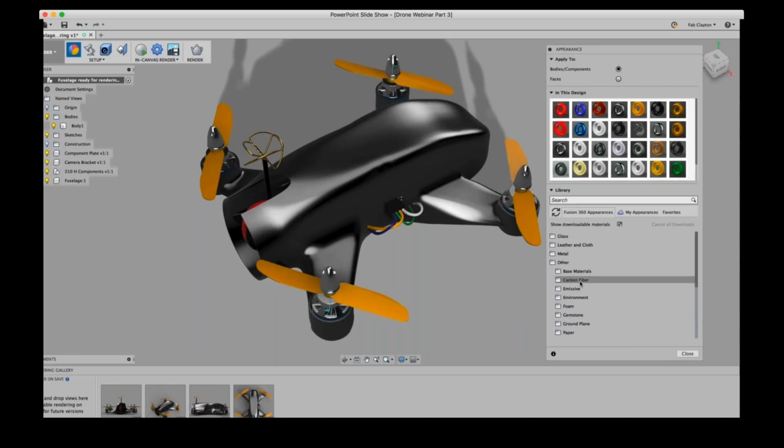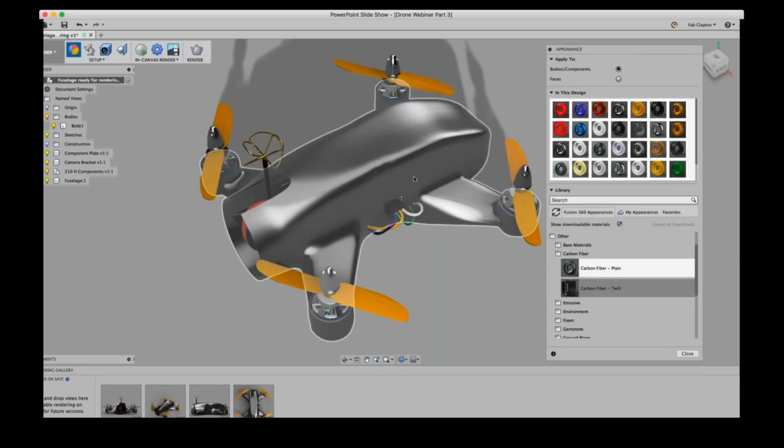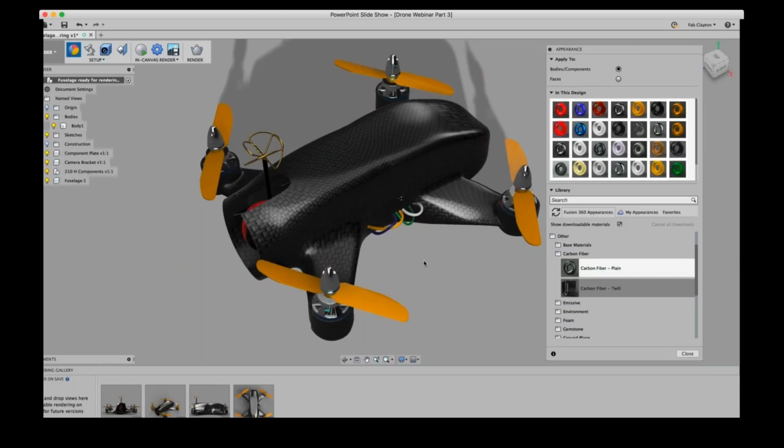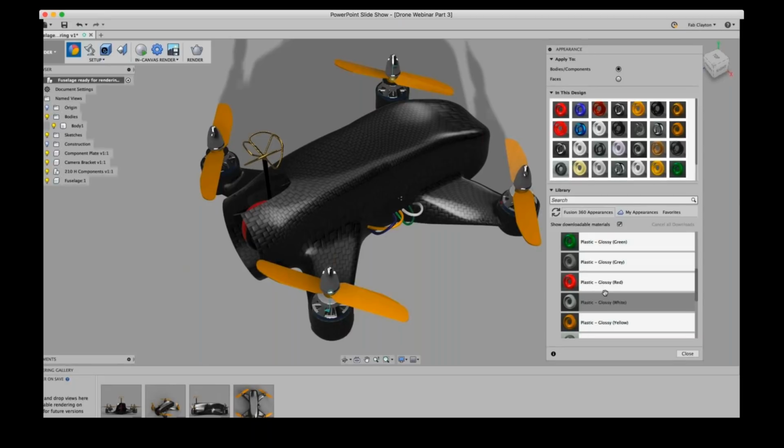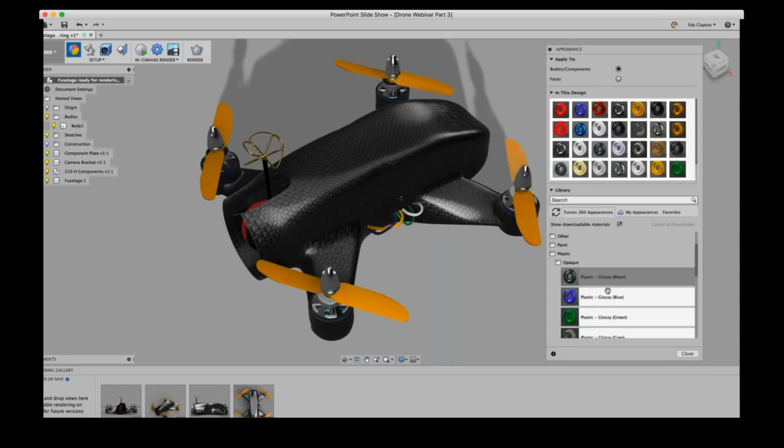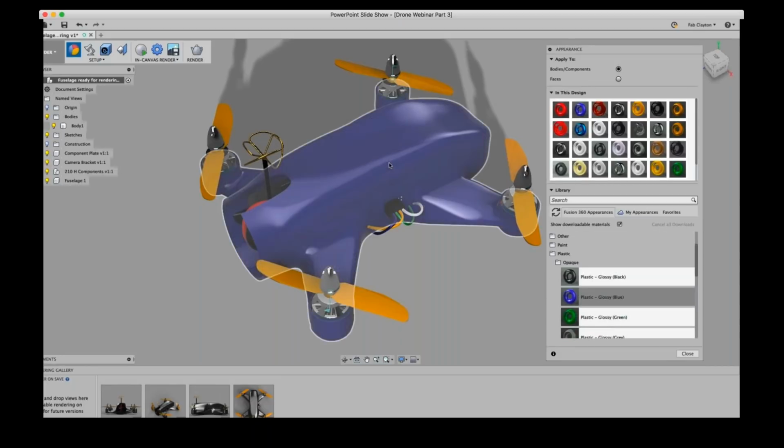So let's select a material. Let's suppose we want to make our body of carbon fiber, but I like the twill, but I don't have it. I'll just click the download button here a little bit, and then I'm going to just drag. It's as simple as that. Just drag to the area where you want the material to be, and then you see it shows the appearance immediately. But of course, I'm not going to make this in carbon fiber. I don't have the material here, so I'm just going to choose some type of plastic, and I'm going to use Autodesk colors. I'm going to choose the blue-green Autodesk colors here. So I'm just going to get a glossy plastic here.